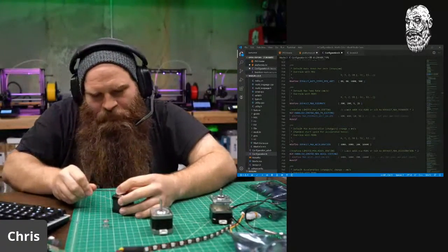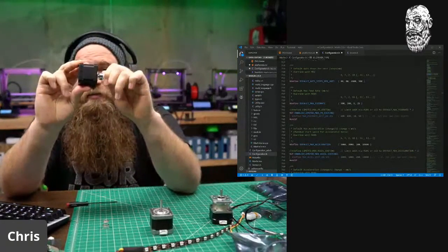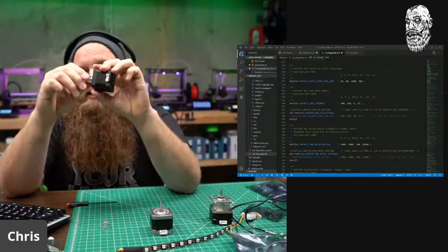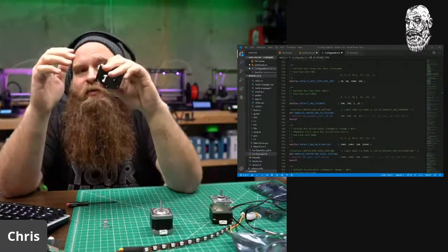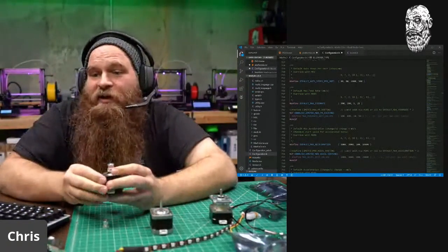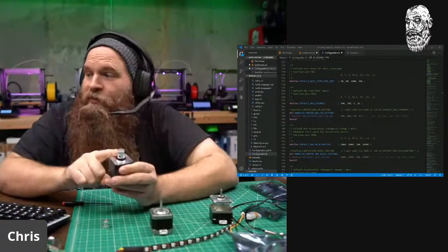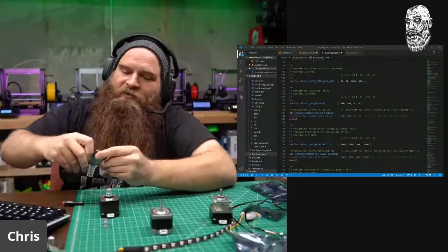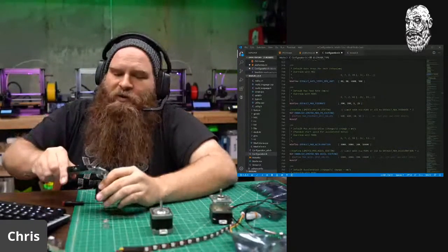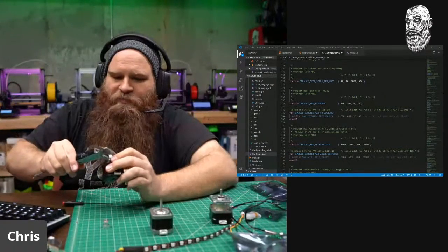So when we attach our pulley to this, we now have a difference in how much length is moved on the belt. There's a website for this, but for a 1.8 degree motor with a 20-tooth pulley, we can measure that if we just grab this and measure the diameter. It should be 12. Yep, so 12 millimeters.